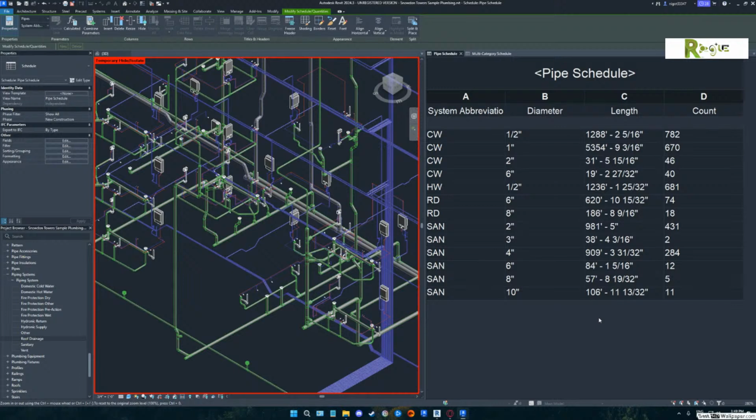And then, of course, if we wanted to see where our roof drains were, you could highlight both of those, but understand you're only going to be getting the pipes. This is only the pipes, not the pipe fittings. We could go into the other view and see where they're at. You got it already. That's why I wanted to run you through that a couple times. Isolate category.